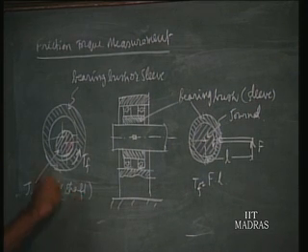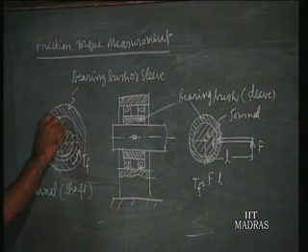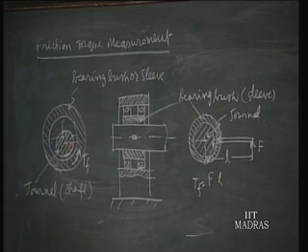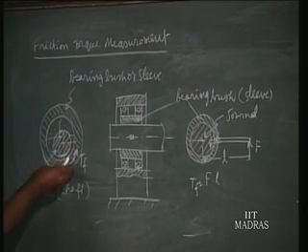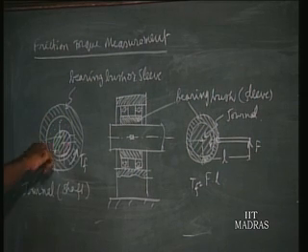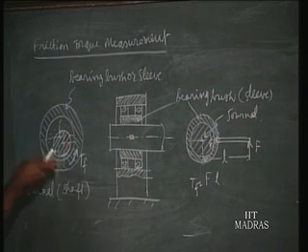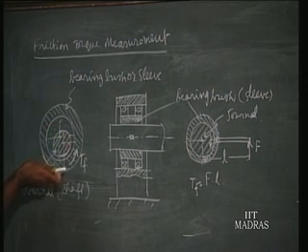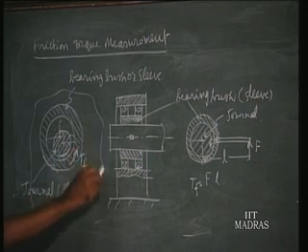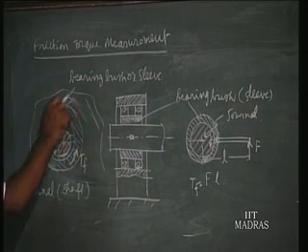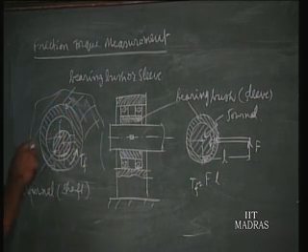The shaft is rotating inside, and we have the lubricating oil. So as the shaft rotates in this direction, because of wedge formation, the shaft is lifted. When it is lifted, it is rotating, but due to viscous friction of the liquid lubricant, the sleeve also will be under the action of the friction torque. So torque will be there. Normally the sleeve is fixed to the wall.